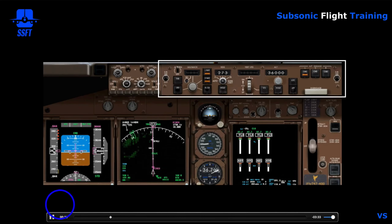The autothrottle arm switch is an arm-off switch. When you turn the autothrottle switch to off, that's a positive disconnect of the autothrottle system. So you can see as we turned it off here, we got the master caution lights. We got the beeper, 1 second on, 10 seconds off. And we got the autothrottle disconnect message on the ICAS alert screen on primary ICAS. You can also see that the FMA went blank under autothrottle. And at this point, we are manual thrust.